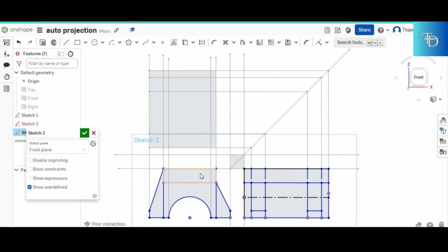So let's look at the front, because we know that from the top you're going to see this part right there, which is the top part. But in the top view, because we can see it from the front, it's going to be where? It's going to be at our bottom. It's going to be at that level right there, because that's where our top should start. So if we are using our special corners method, our top is supposed to start from there. Now let's go over and outline what we can see and what we cannot see.